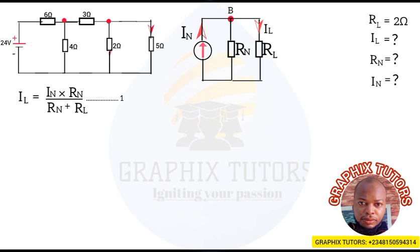Before we analyze this circuit, I have to label it. I'll label it alphabetically to enhance our understanding. So this point here will be point A, point B, point C, point D, E, F, G, and H. Now, let's kick into business. For us to calculate the IL, we need to know IN and RN. So let's start with RN, that is the Norton resistance.